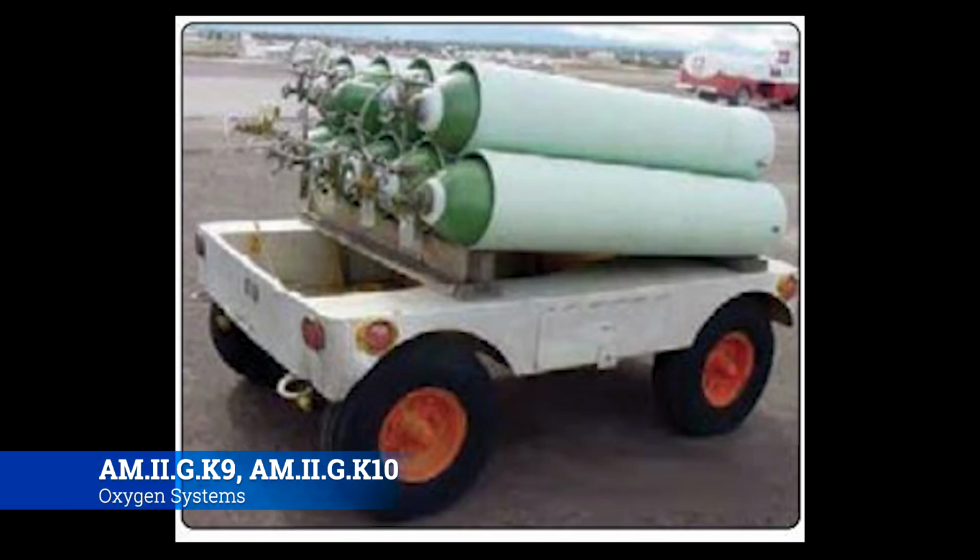All right, so let's talk about oxygen servicing one more time. This is the process that you're going to go through whenever you're servicing an aircraft oxygen system. You're going to check all the hydrostatic dates on all the cylinders, and make sure that they're within date. You're going to make sure that they are above 50 psi, so they have enough charge in them to get you where you need to go on that aircraft. You're also going to make sure that the refill cart is grounded, so you don't have to worry about any sort of static discharge causing an oxygen fire.